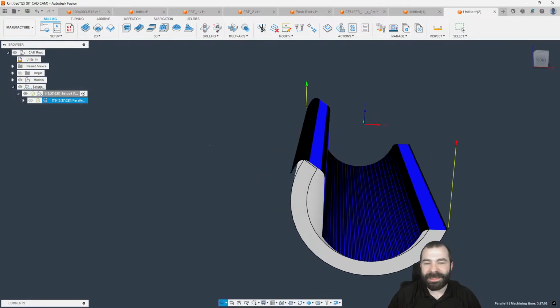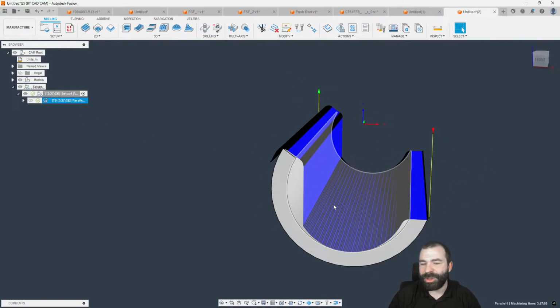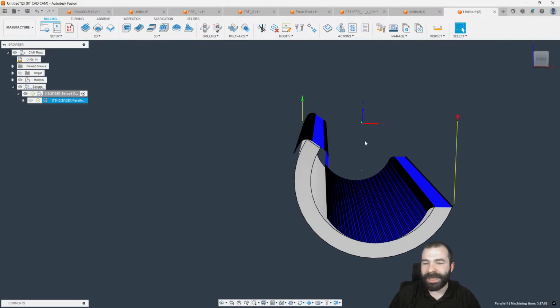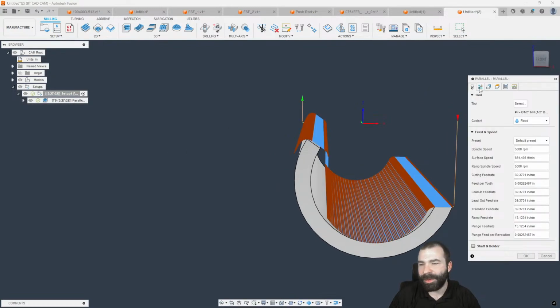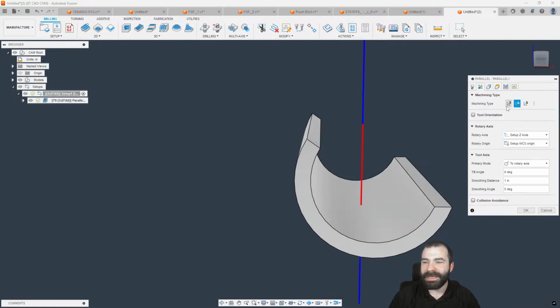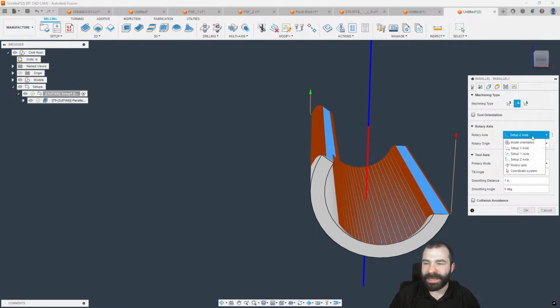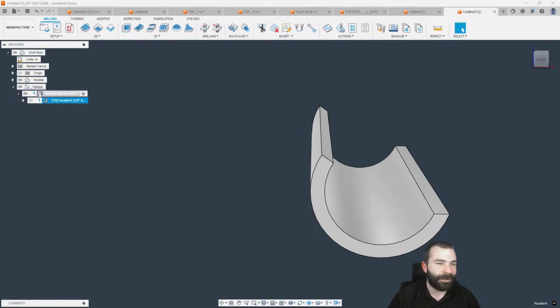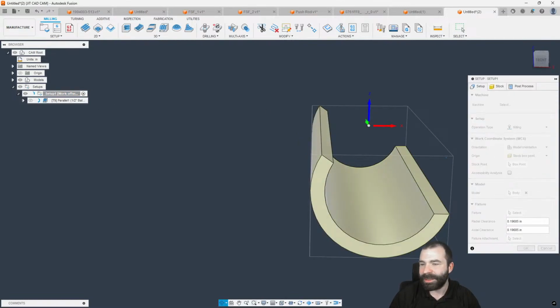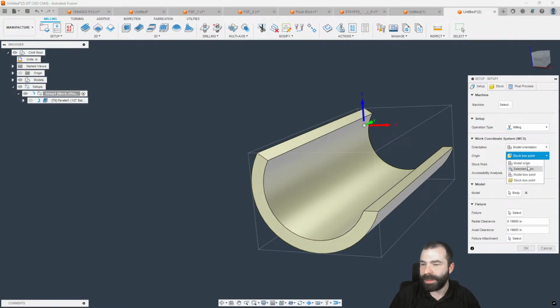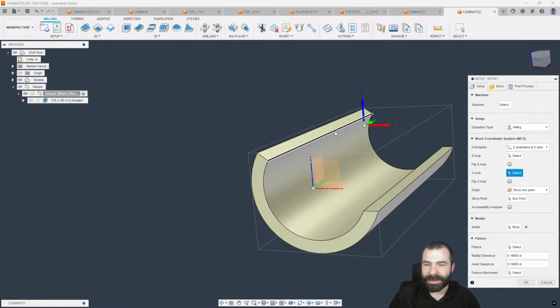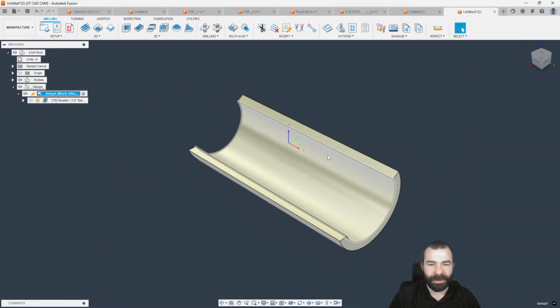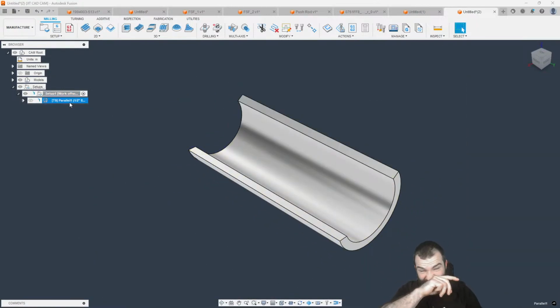So as you guys can see, this is trying to machine inside of a part. Now there's a lot of tricks to this and there's a lot of things that can be painful on a part like this. If we went to 4-axis and then we set our rotary axis based on our X, in this case, I need to fix my setup. Bear with me, guys. We actually want our X axis to point down our part. And there we go. Let's set our X-axis this way. Means our toolpath will change what it does, right?